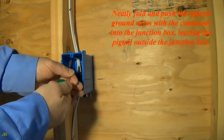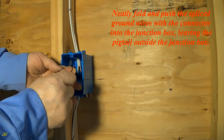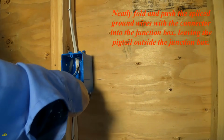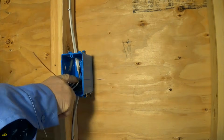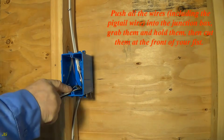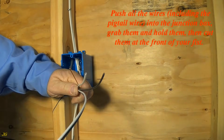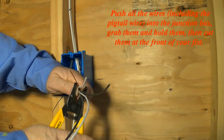Neatly fold and push the spliced ground wires with the connector into the junction box, leaving the pigtail outside the junction box. Push all the wires, including the pigtail wire, into the junction box, grab them and hold them, then cut them at the front of your fist.